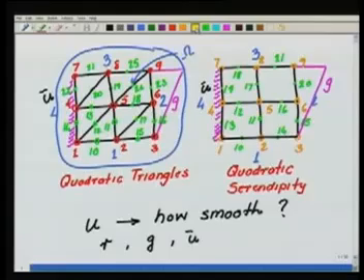We could decide to refine the mesh, that is, break the existing elements into smaller, uniform pieces. This will be my new mesh, which will have 4 into 4, 16 elements. So out of a mesh of 4 elements here, I have 16 elements. If I do it for triangles, I will break the existing triangle into 4 equal triangles.